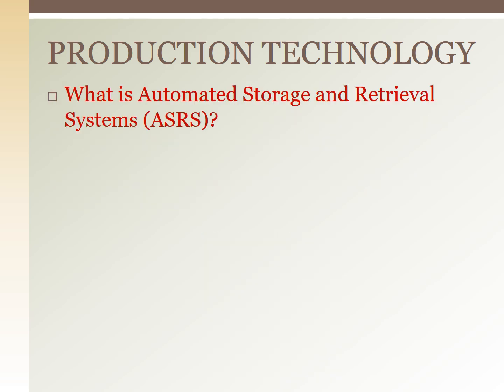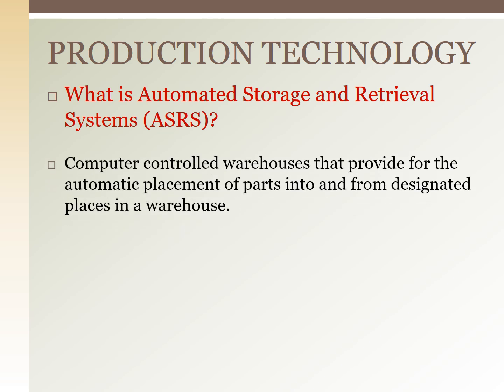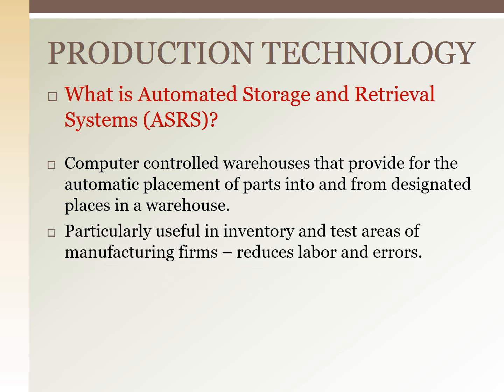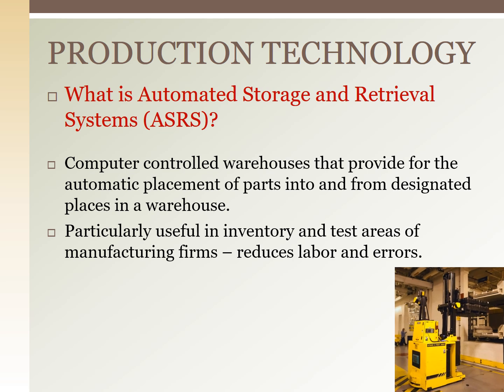Automated storage and retrieval systems are computer-controlled warehouses that provide for the automatic placement of parts into and from designated places in the warehouse. So you can look in the computer and know exactly where those parts are in which bay. It's very useful in inventory and test areas of manufacturing firms, and it reduces labor and errors.